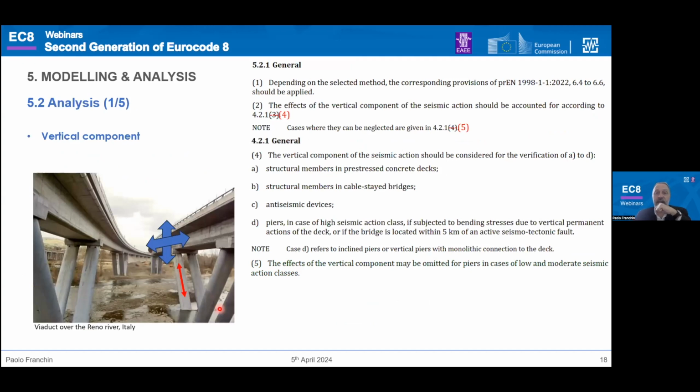Finally, a few slides on analysis. The vertical component of the seismic action can be omitted in low and moderate seismic action classes, and should be considered instead when you are verifying structural members of pre-stressed concrete decks, because of course pre-stressed members are sensitive to vertical loads, or you have structural members in cable stayed bridges where you have the inclined stays and important